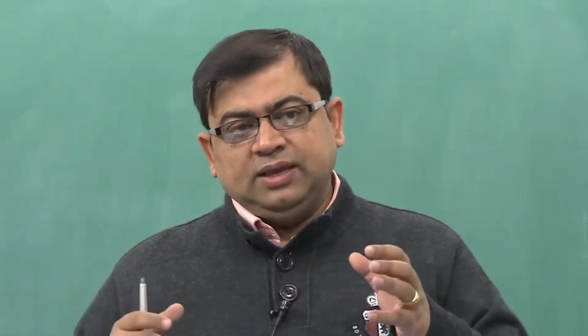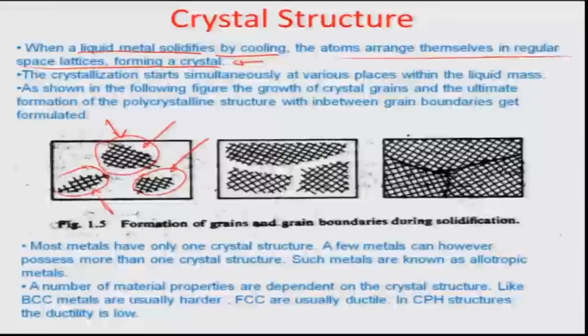Unfortunately, the crystals are growing, because of the randomness of such nucleation sites or centers, in all possible directions, and therefore at some point of time the crystals would go against each other. For example, in this case the crystal is growing in a different direction, as you can see from this nucleation site, and the crystal from this nucleation site is going in a different direction, and they are going to sort of face each other and not be allowed anymore to expand in the regular direction.